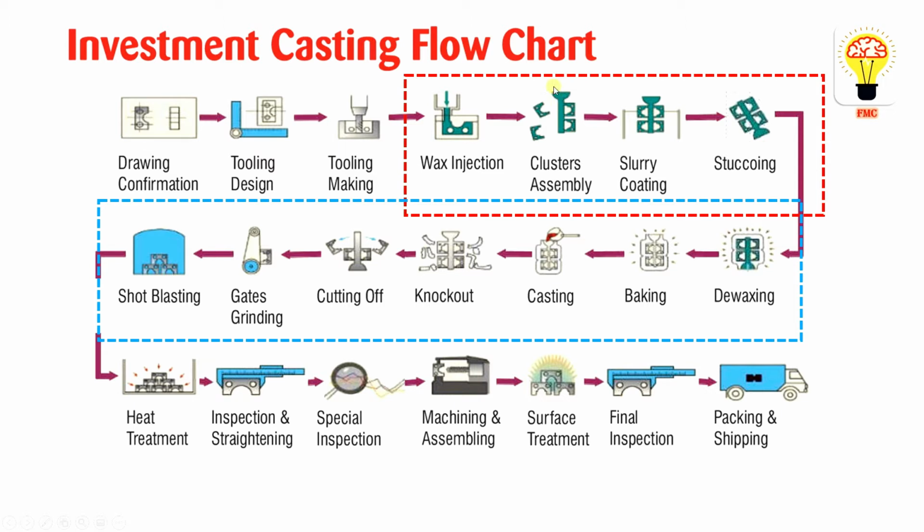And you can see this portion is the top here, and here it was tilted over, and finally it is put in a downside shape, so that the wax will come down. You will get the perfect shapes. When the shape is available and there is no wax, then we are going to pour the molten metal over that shape. Remember, this is made up of ceramic, so it can withstand high temperature, nothing to worry.